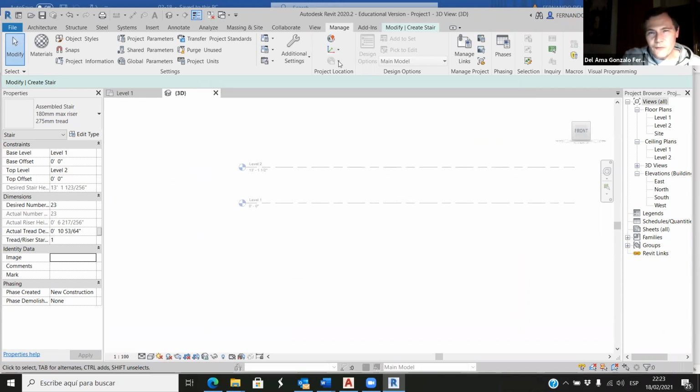So first, you have to get used to defining the units, the project units, and then the location. Sometimes I'll forget, I will open a drawing and start drawing, but you have to get used to doing this because it's important. We have to select the project units and we have to select the location. And then